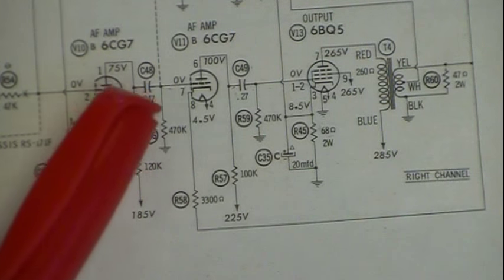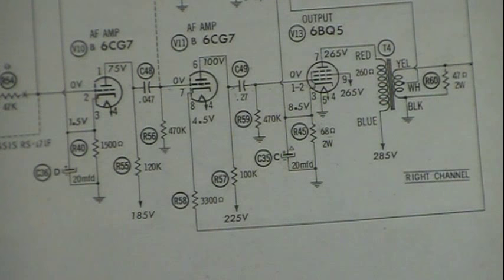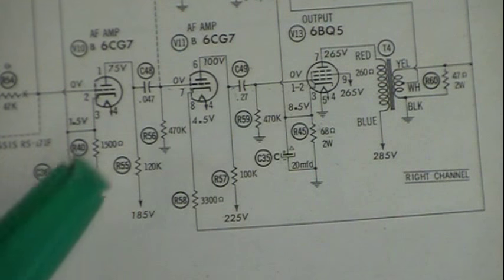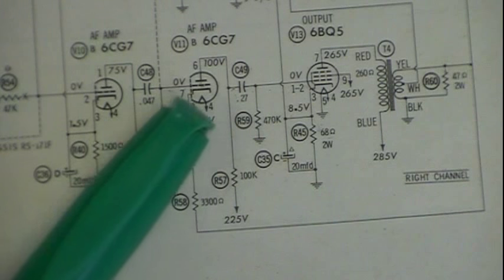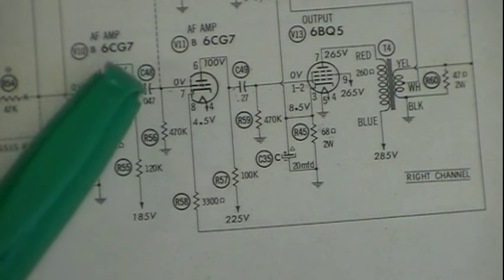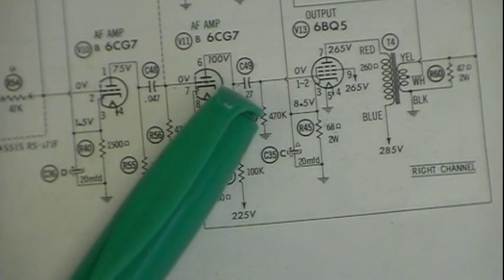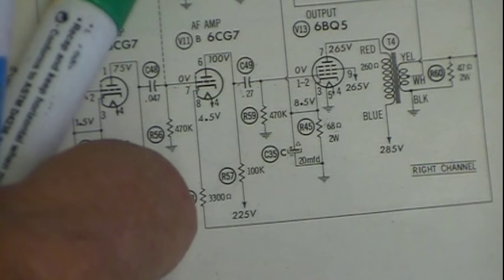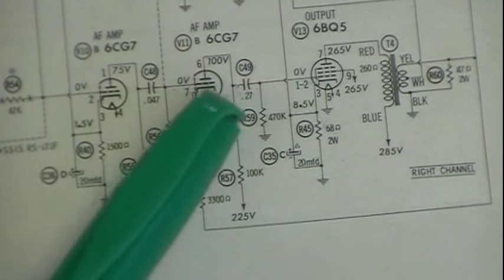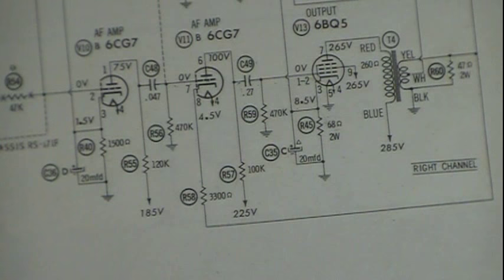So my guess, if I was to reckon a guess, is the coupling caps to the grids on both of these probably went extremely leaky or even dead shorted. The possibility also exists that the coupling going to the output tubes also were leaky and helped along with this. But that's the reason why they went out. It was more like signal current than actually DC current.